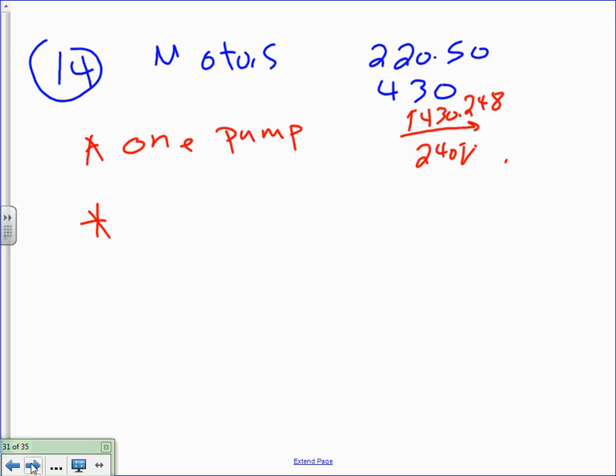Okay, motors. How many motors do we have? 1 ton. And what was the size again? 5 horsepower. Okay, 5 horsepower from Table 430.248 under 240 volts. What's the full load amp with that? Two gentlemen agree? 28. Anybody disagree with my friend? Everybody agrees with that? 28. Then that's a piece of cake. That's for my motor, right?